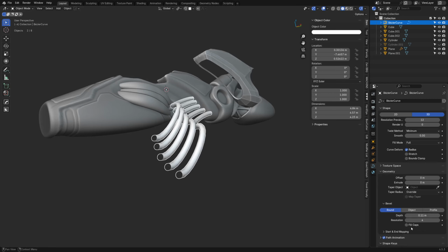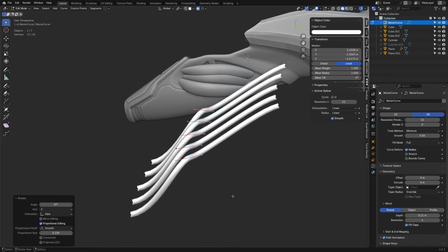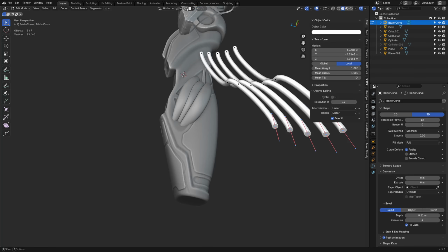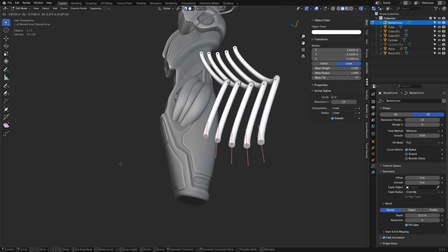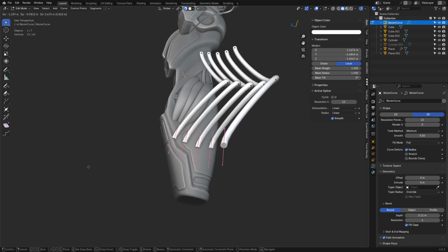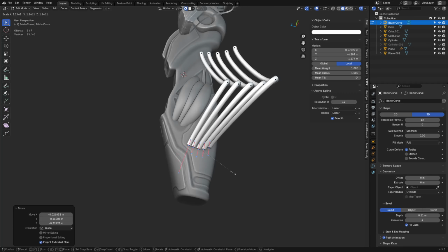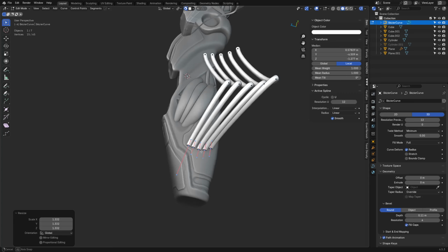The depth here, fill caps probably. And you can see those are all intersecting, so we can unravel them, perhaps. Do something like that. Maybe move these around, and try snapping these as well. Say, base project, rotation to target. Do that. Snap that surface, right? Scale them in, maybe. Set this to medium. Scale it in. See how that works. Really cool what you can do here between those two settings, individuals, medians, and also possibly 3D cursor.